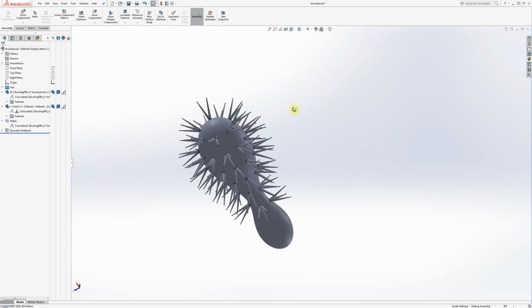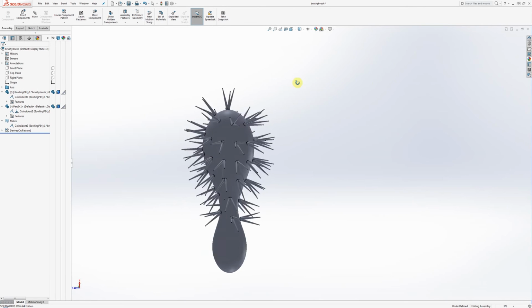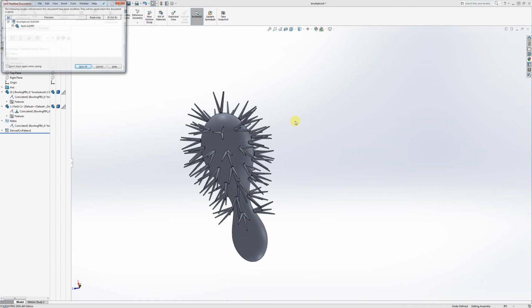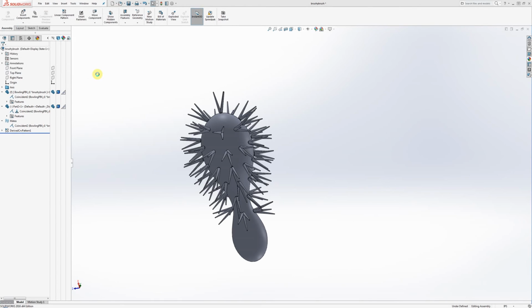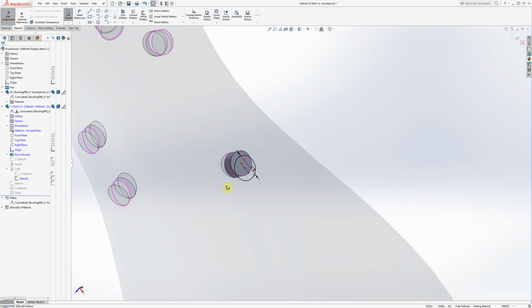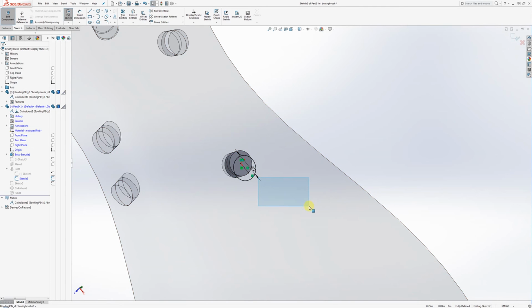Okay. So this thing's really fun. Now I'm going to save my work. I'm going to save all the parts involved. Okay. And the reason why this is so fun now is because now I can go back and I can make edits to the individual components. Like, see how I've got a little 2mm. I can change this to 4.